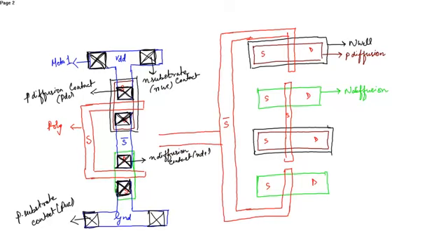And from here we need a metal layer. So there is overlapping between the metal and the poly layer. So we have to place a poly contact over here. So this is a poly contact.